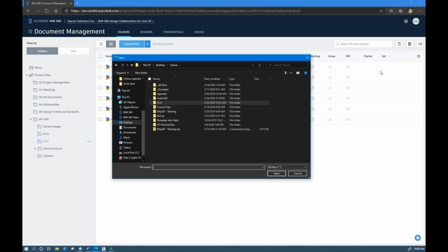Yes, if you have your folder structure set up appropriately, where everything that it's looking for is pathed within that project folder, it should maintain those paths for you. But with XREFs, you may need to update them manually in some cases, and the data references, again, if not set up appropriately, it doesn't support that hybrid environment. It needs to all be through BIM.